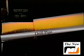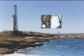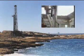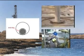Here, the addition of pipe rotation at 150 RPM effectively stirs the cuttings into the flow regime. Notice the hopping motion of the cuttings as gravity pulls them back out of the flow and the pipe movement pushes them back up. It's not just rotation that pushes the cuttings into the flow regime, but a combination of high rotary speed, pipe eccentricity, and mud rheology.